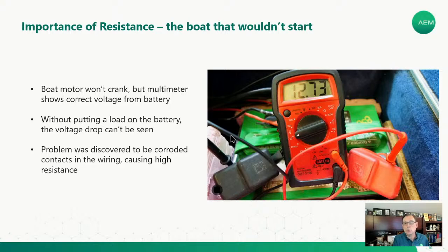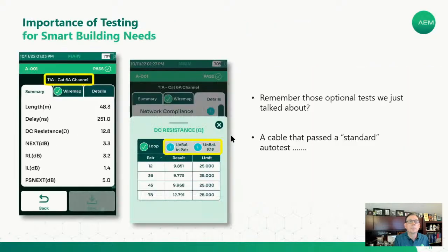So what was happening was there was too much resistance, so we weren't getting enough voltage at that endpoint to turn that starter motor to get the boat motor going.